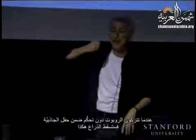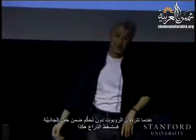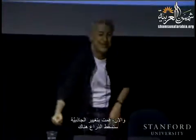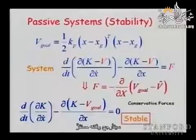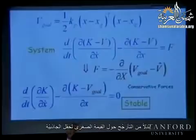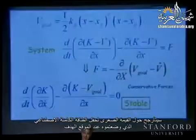Instead of having the robot without any control, where you drop it in the gravity field and it falls like this, now I'm changing the gravity, and it's going to fall there. This system is stable. It will oscillate about V goal. It will oscillate but stay stable. Instead of oscillating about the minimum of the gravity field, it will oscillate about the minimum of the artificial potential field you are putting about your goal position.